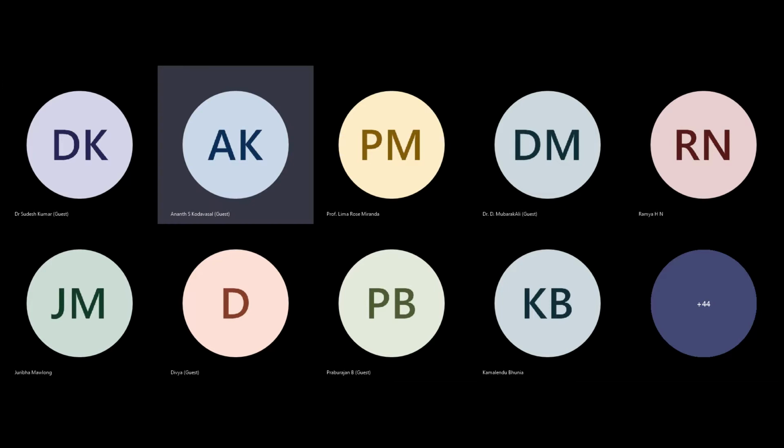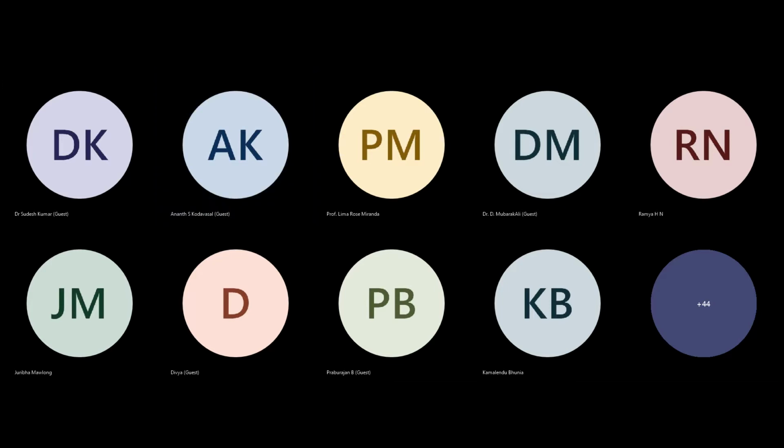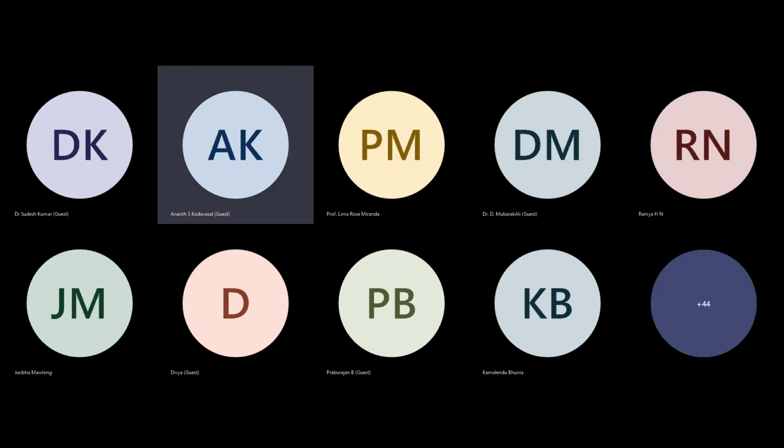Yes, sir. One more question, sir. Yeah, sure. Sir, actually, in the electroplating industry, did you use electrolysis process or some other process? No, it is chemical treatment only, not electrolysis. Okay. Different elements, different treatment. For chromium treatment, we use bisulfite, reduce the hexavalent chromium to trivalent chromium, and then settle it at high pH as chromium hydroxide. Cyanide was separately treated and then mixed. So different treatment. Nickel is straight away nickel, depending on the solubility curves, you can basically precipitate at different pHs.